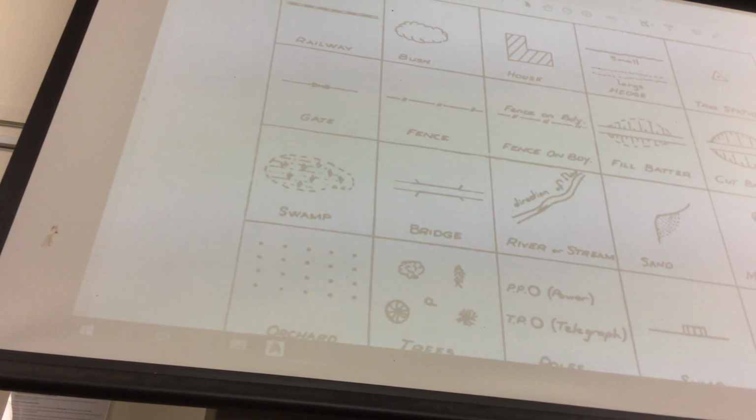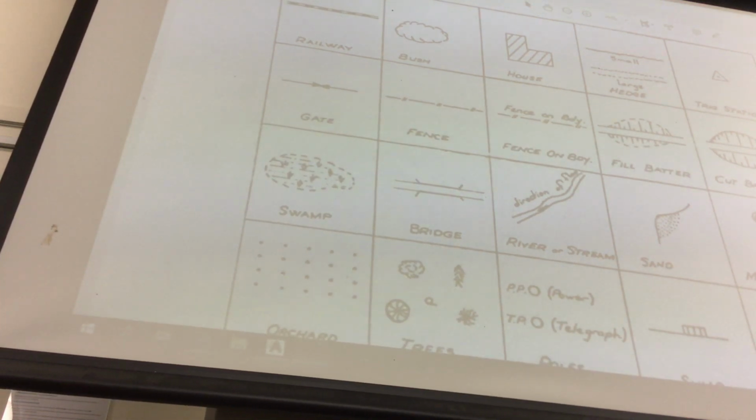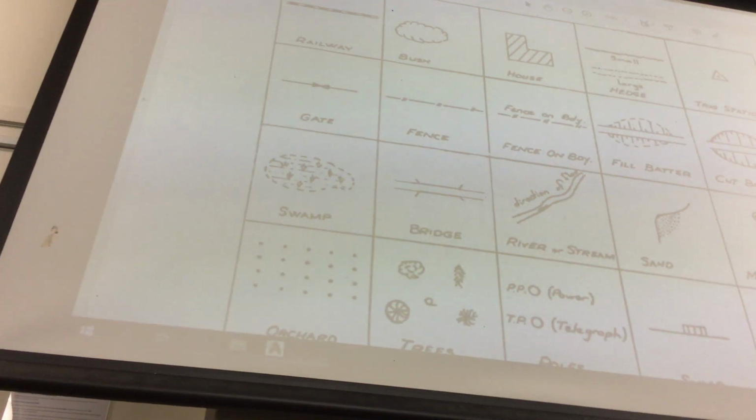There is a swamp. Actually, it's more like a wetlands, and because it's winter, it's more prevalent than it is at the beginning of the year. So this is what I want you to do. I want you to hatch using the dash hatch, and then I want you to do a hatch on top of that using the one, I'm not sure whether it's grass or swamp, you will find it in there, and I'd like it every second one. So you need to set the scale so it's right.